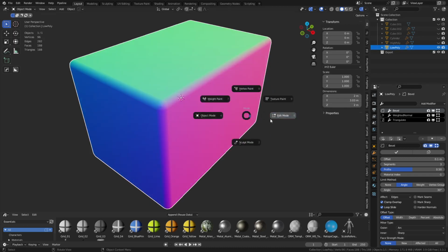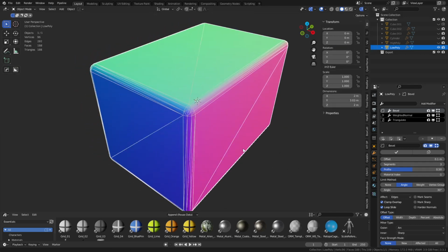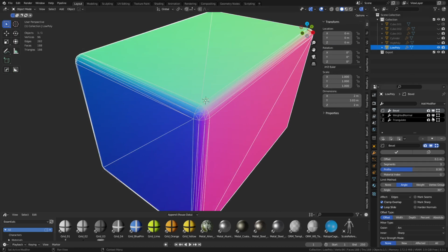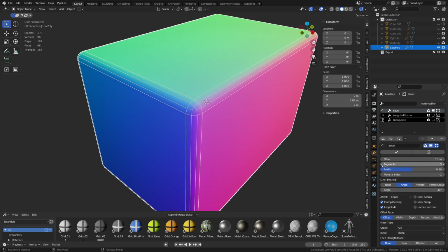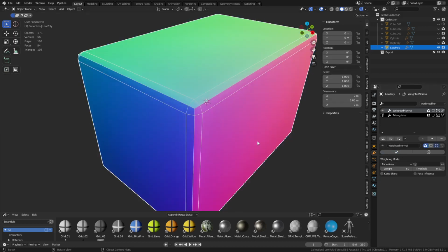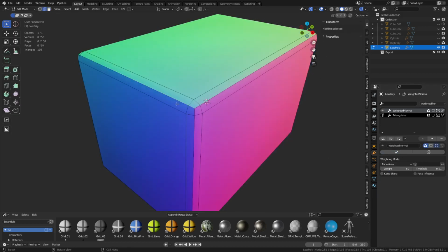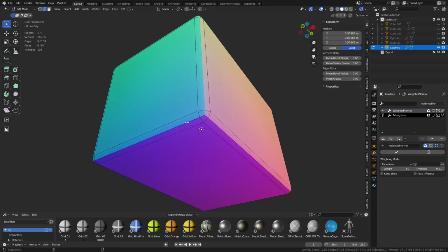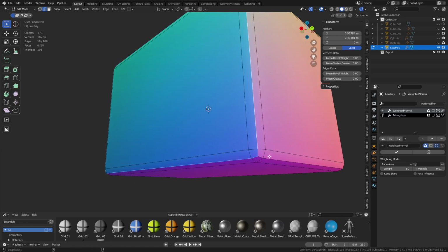And so now what ends up happening is that we can't UV map it appropriately. We need to make sure that we pick a good number here for the, we'll turn these two off as well real quick. We need to pick a good number of segments, in this case 2, where we have this little center line going on, right? And then we can collapse this bevel by hitting Control A over the modifier, hold Alt, and then Alt Shift. You could select all of these super fast and unwrap this thing.